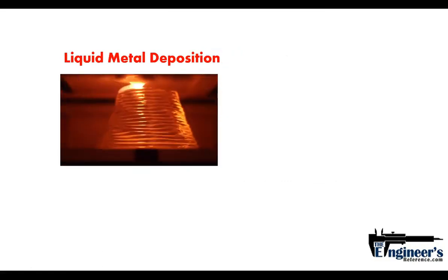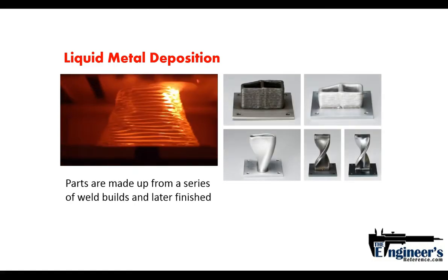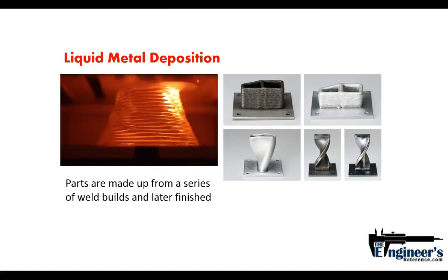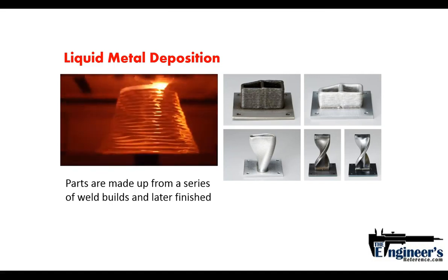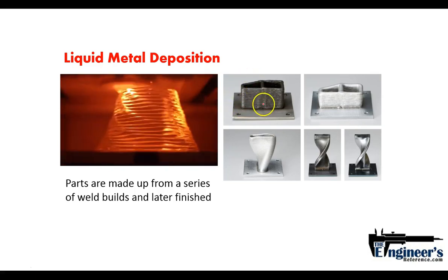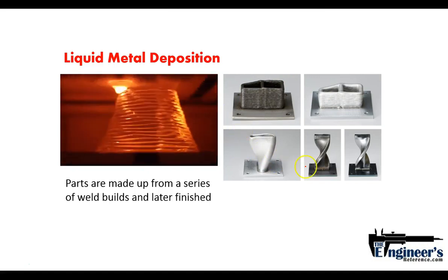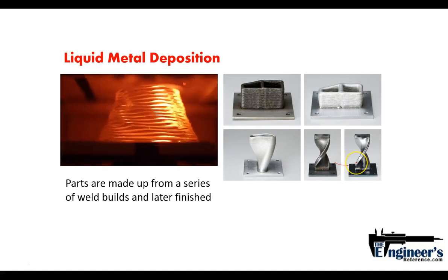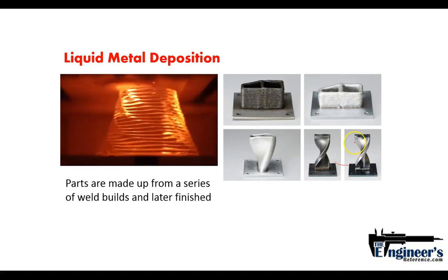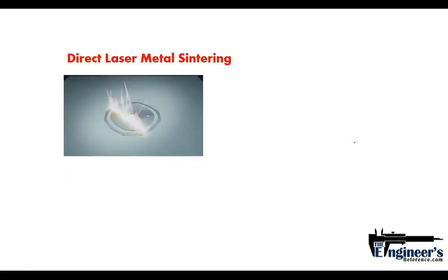Now this is another one that a lot of people are probably more familiar with, which is liquid metal deposition. Again, you're taking a powdered metal, and as you build it up, it's almost like weld that you're building a component, and this does require some machining and finishing. Since it's done in various layers, you're not going to get a really pretty surface finish. As you can see here, it's being built up, but you can finish it. It does require some finishing operations, grinding operations, and some minor machining operations, and you can get a nice surface finish, but it does essentially add another process to get the surface finish that you like.